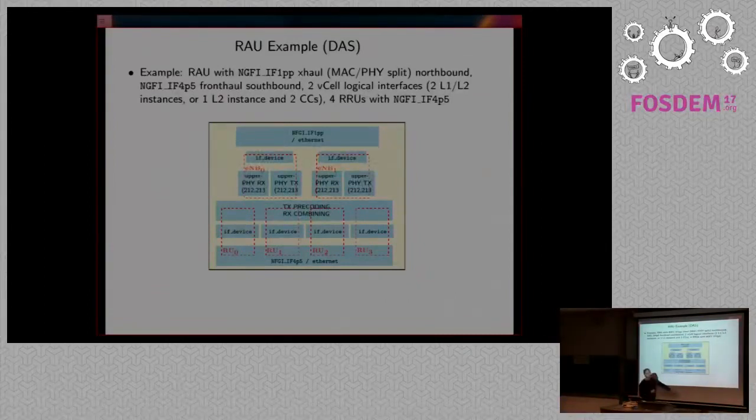So you have an optical link there and an optical link here. But this signal processing is happening somewhere in the middle of the deployed region. So in this unit, I've put in two base stations, or two logical base stations, two eNode Bs, which are running the physical layer signal processing of two base stations, and it's connected to a precoder which is driving 4 radio units. So here's a mapping of 2 base stations to 4 radio units.